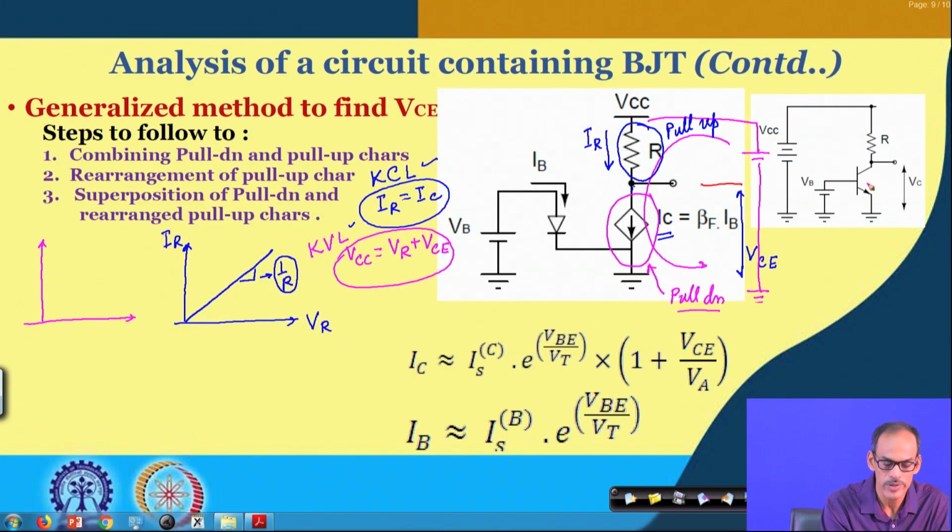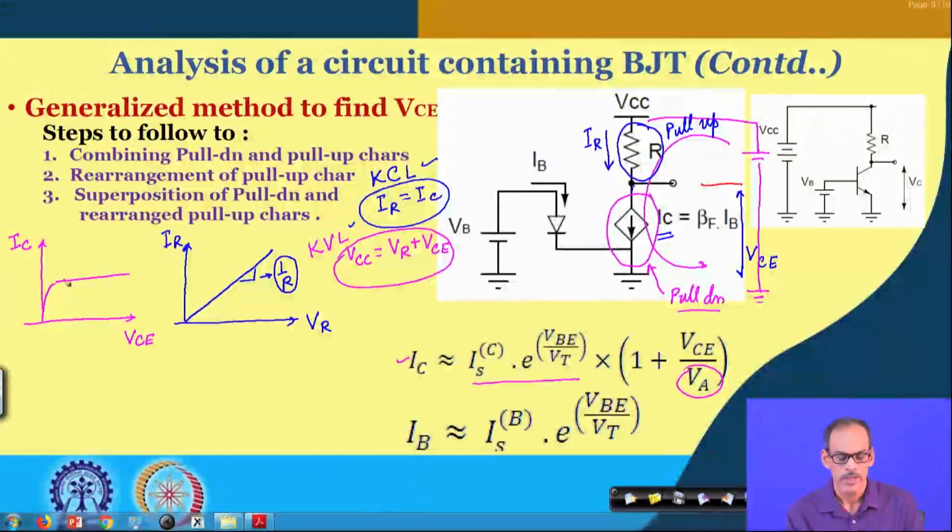from the device equation we may write, say, IC as a function of VCE. So, as you can see here, for a given value of VBE, if the early voltage is very small, we can say if the device is in the active region of operation, the IC has hardly any dependency on the VCE voltage. So, you may say that it is practically flat. Now, okay, so these are the things we have in our hand, and